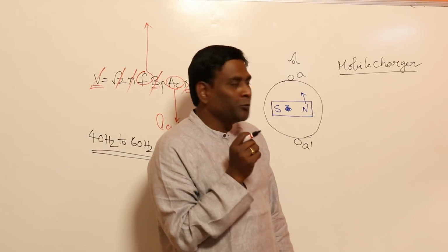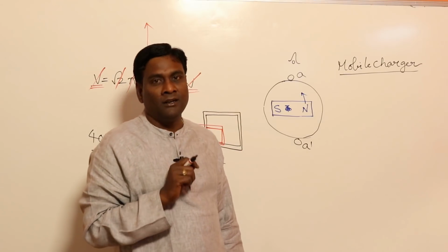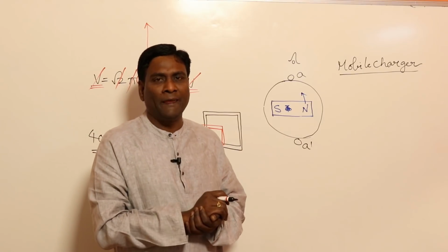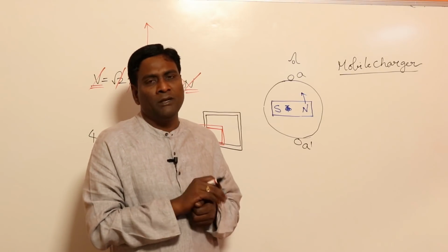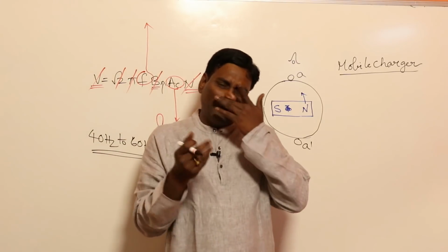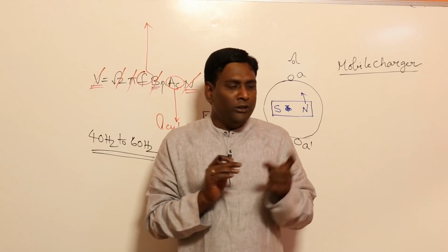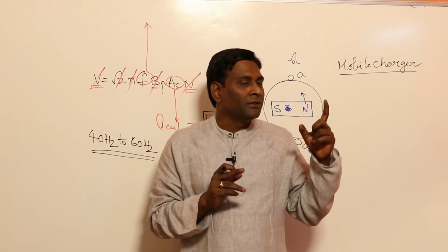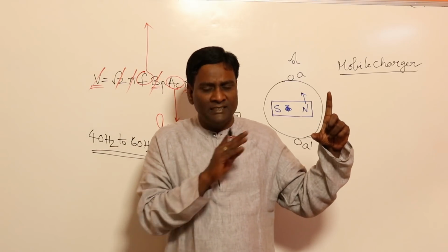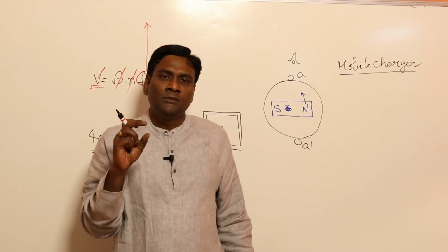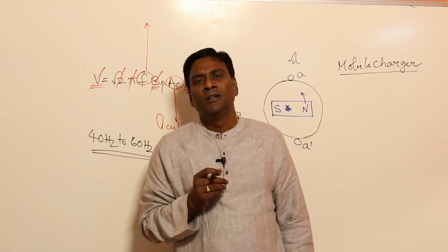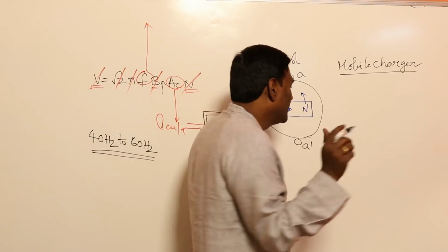Okay, once we discuss this, all dots will be connected. For example, a normal mobile charger, how it should ideally be: we supply a 230 volt supply, and the output voltage should be roughly 5 volts DC. In order to reduce the voltage, focus here, all of you please. If we want to reduce the voltage from 230 volts, some significant amount of AC voltage, to less voltage, and then give that lower voltage to a rectifier, it will give DC. So we can use that for the charger.